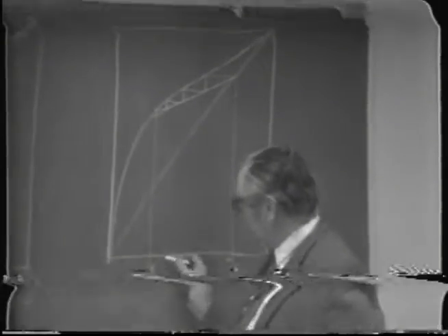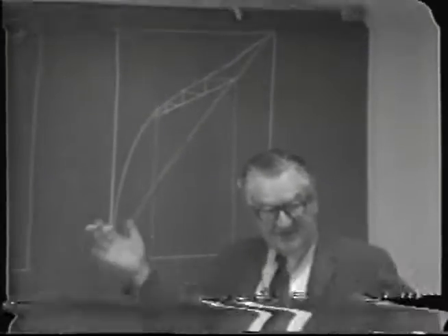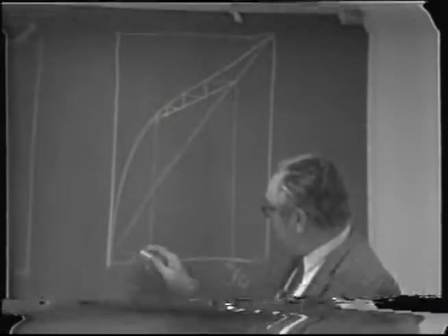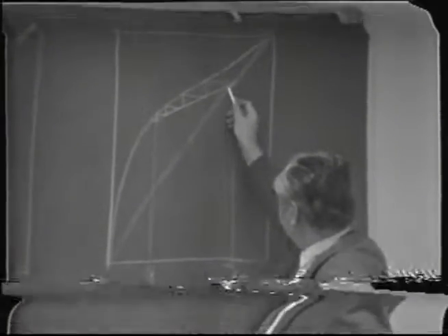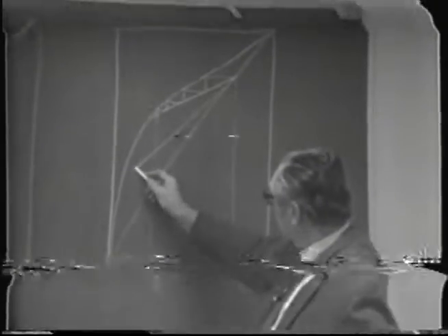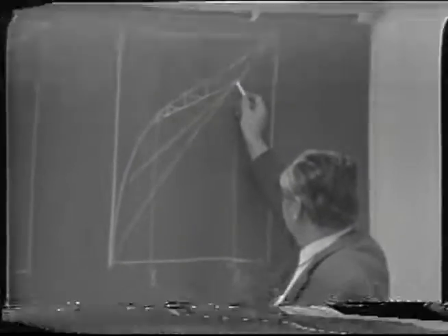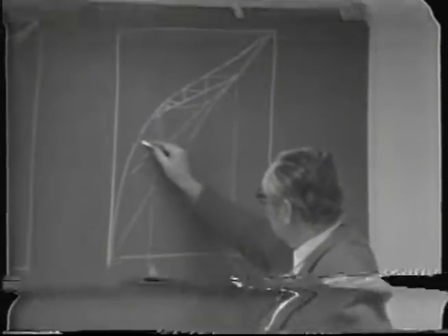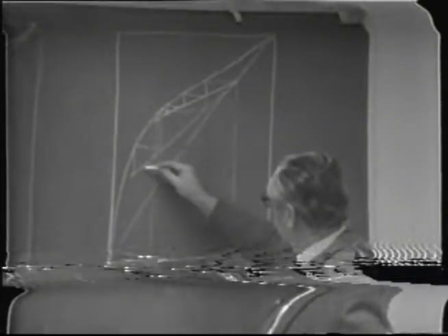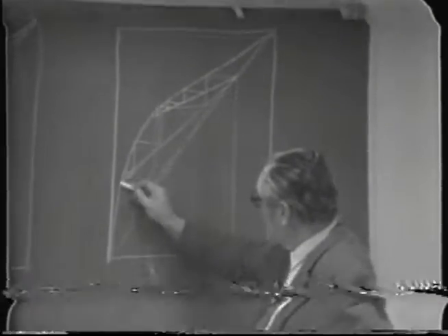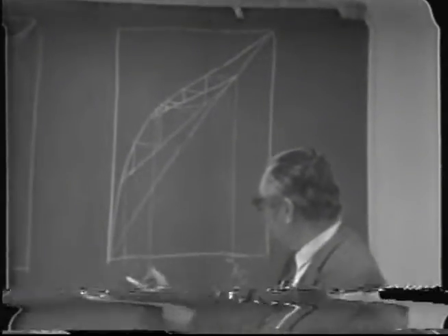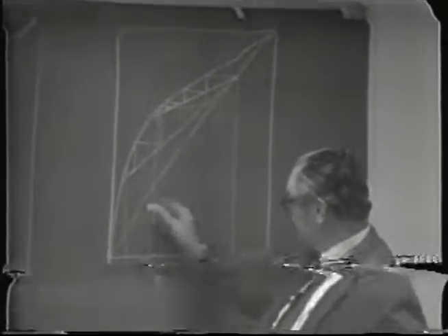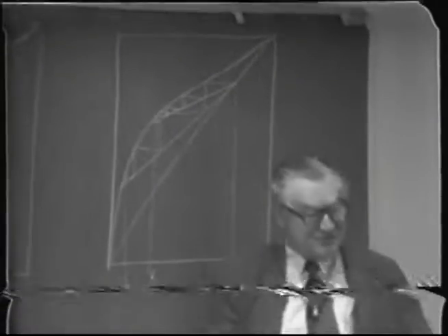Now, as the concentration decreases during the run, as you take out more of the volatile in the vapor, well then you would have to increase the reflux ratio. So now we'd have that many. This would be the concentration in the pot, which would enable you to get this distillate concentration with this reflux ratio. You see.